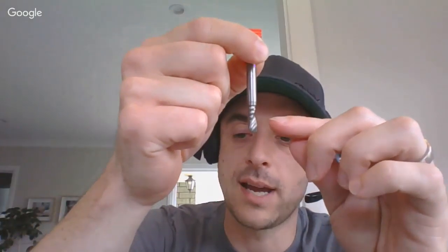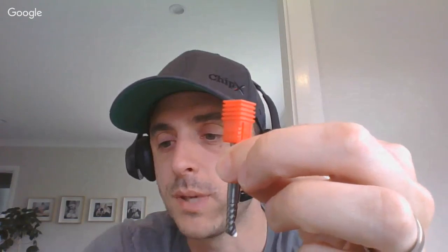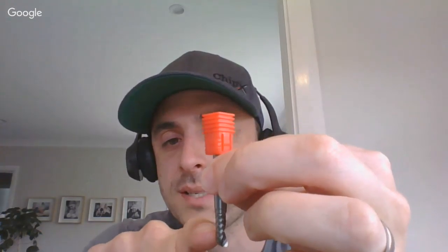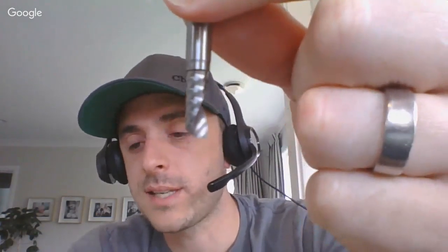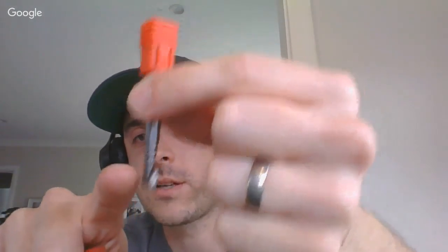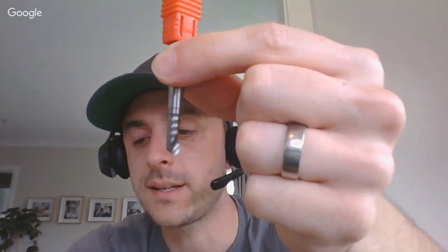But a nice way to think about it is, when you get a formula that works for the 6mm, which might be how much of a step down you can take, look at that step down as a percentage of the diameter of the tool. So Brett said he's had some success with 4 to 6 mil. If we pick 6 mil because it's the easy example, that's a 6 mil diameter tool. He's doing 100% of the diameter as the depth of cut, so we'd call that a 1D cut. It's 1 times the diameter in depth. So the equivalent cut for the 3 mil is going to be a 3 mil deep cut. So if 1D works well for that, 1D will probably work well for that as well. And then the feed rate will be the thing you adjust to suit.